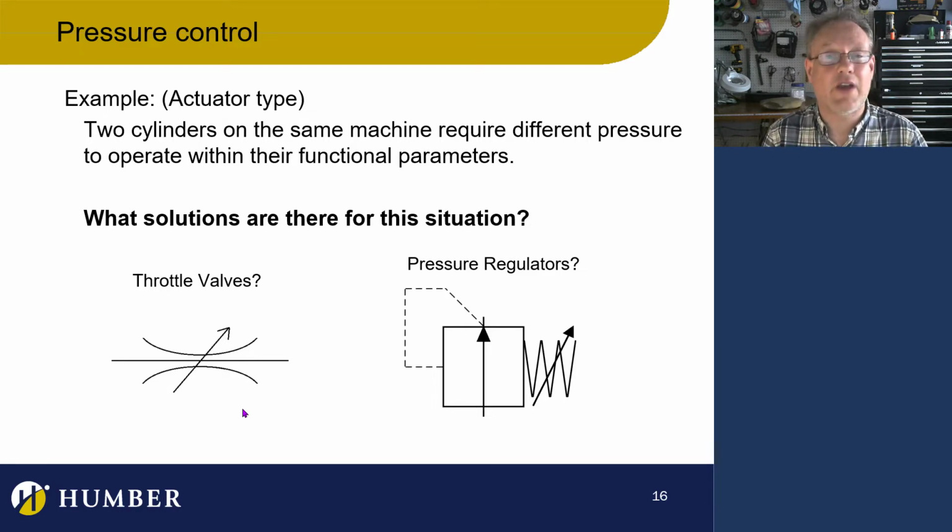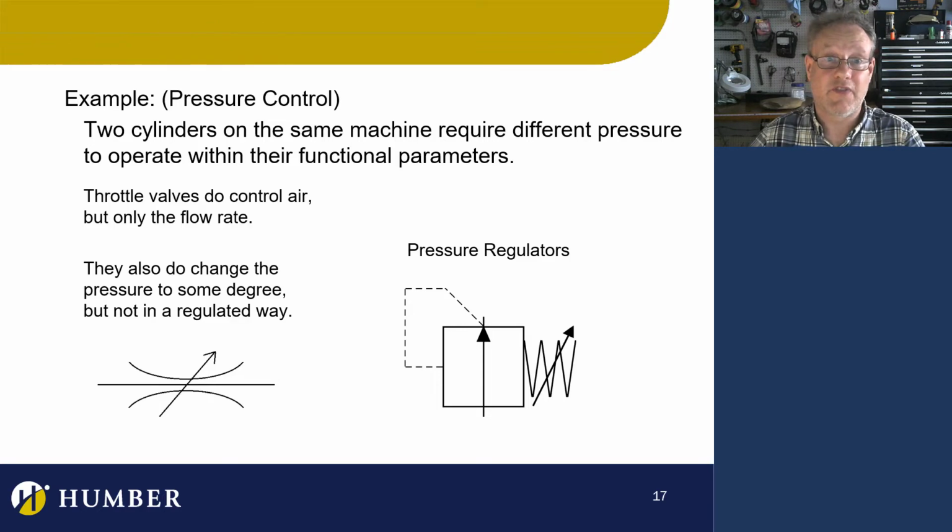It's very inefficient. But you'll also see that if there's a pressure drop in your system somewhere that you're not expecting, you're like, why, man? I've got the pressure regulator set to 80, but 20 feet downstream there are some things that are working, but they're only working at 75 PSI. What's going on? It's probably a leak in your system. So leaks also create pressure change. And if it's a controlled leak, like a pressure relief valve, then that's actually controlling pressure. But typically we don't use this to control pressure all the time. In a pinch, we can control overpressure with pressure relief valves.